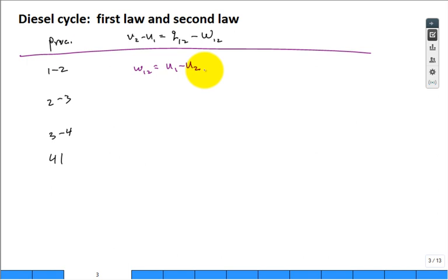How about we write the general form of the second law for a process? It would be the final entropy minus the initial entropy, so that's the entropy change, is equal to how much entropy is transferred in with the heat, integral of delta Q divided by T. You can put a B on there because it is the boundary temperature at which it's being transferred in. And then we have plus sigma 1 to 2. So if it's internally reversible and adiabatic, we conclude for the process 1 to 2 that S2 minus S1 is equal to 0. It's isentropic. So that's a big conclusion.